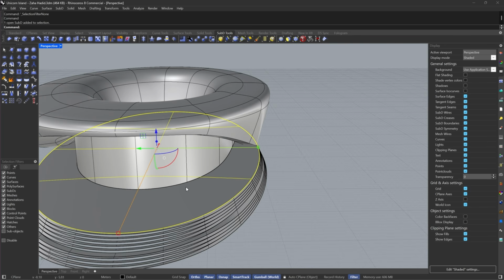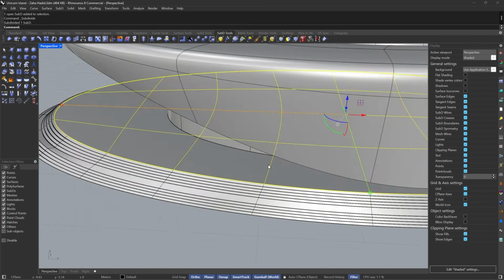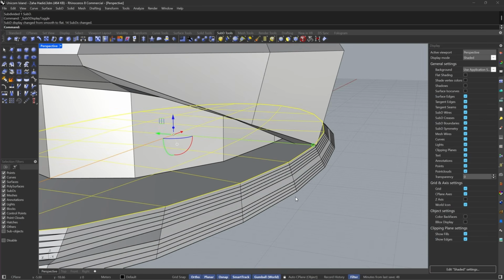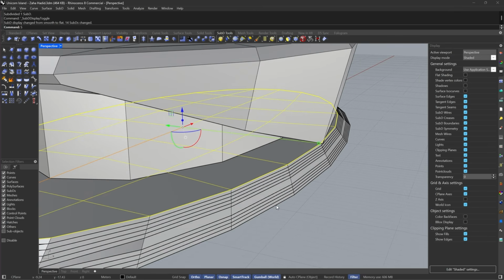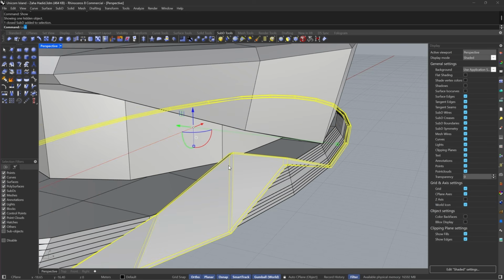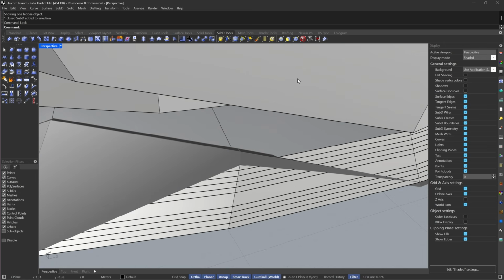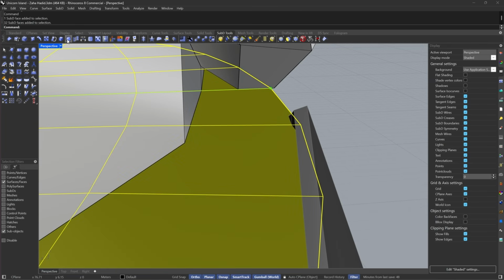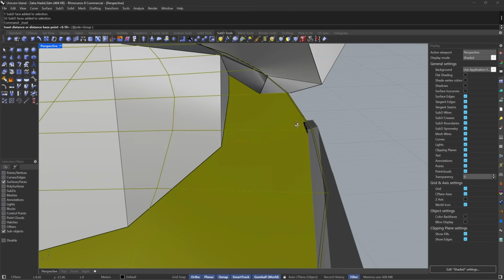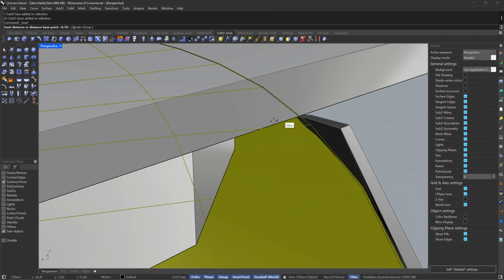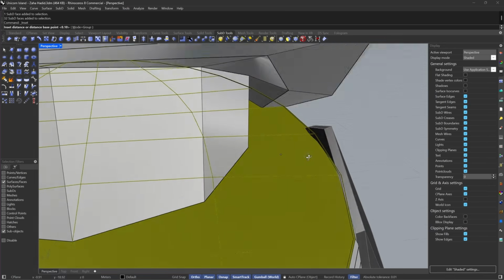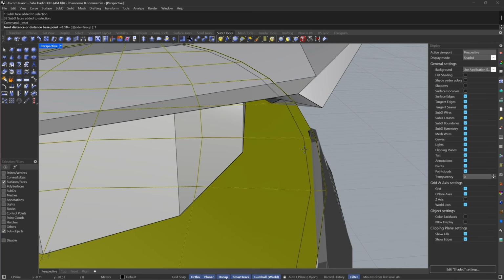So first thing I want to do is to add more subdivisions to this so it will fit perfectly with this. So if something is moving, this will move with it. And after that, let's show and let's lock this for a second, and let's see what we can do about this part. So firstly I want to select all of these and just add an inset a little bit, because I don't want the inside bar to move, but maybe like this exterior vertice to move. So for now I'll say 1 maybe.